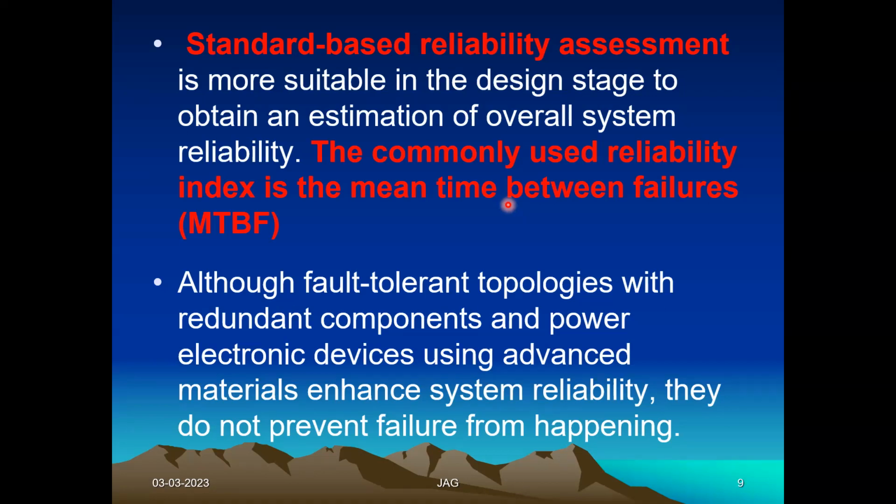What is MTBF? Mean time between two failures. So that is statistical data. Every component, say I am using IRF 640 MOSFETs or TMS 320 microcontroller, all of them will be having an MTBF, mean time between failures. That data usually will be given by the manufacturer. So the manufacturer will be tracking his product out of the experience and the feedback he is having. He will be having this MTBF information that will be published on the website. So you should use the component which is having higher MTBF.